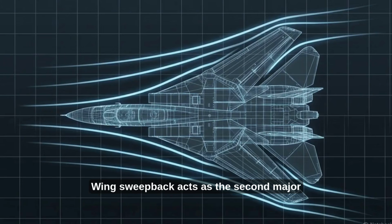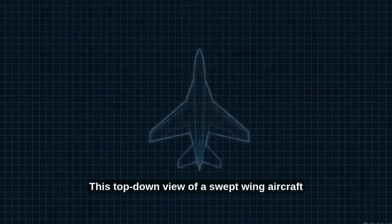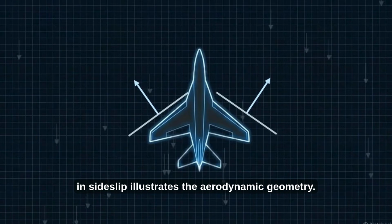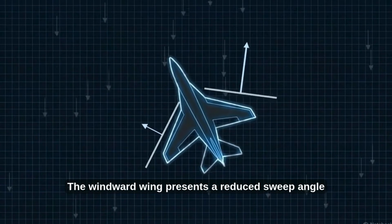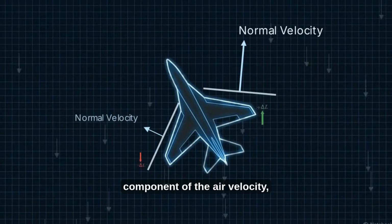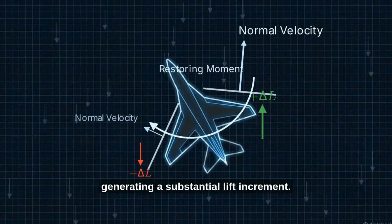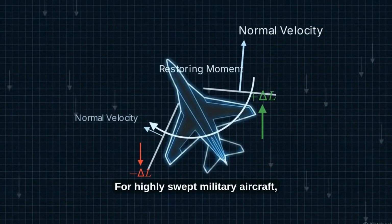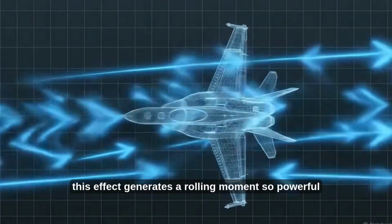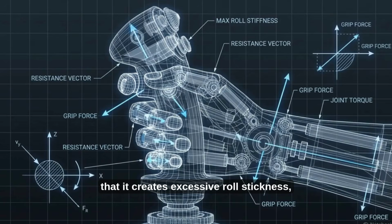Wing sweep back acts as the second major configuration variable that functions as a powerful, effective dihedral. This top-down view of a swept-wing aircraft in sideslip illustrates the aerodynamic geometry. The windward wing presents a reduced sweep angle to the incoming air. This drastically increases the normal component of the air velocity, generating a substantial lift increment. For highly swept military aircraft, this effect generates a rolling moment so powerful that it creates excessive roll stiffness, making the aircraft resistant to pilot inputs.